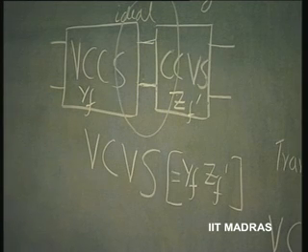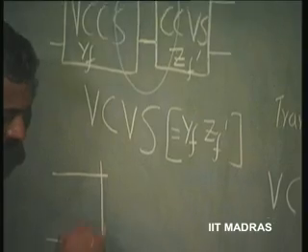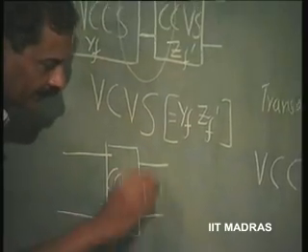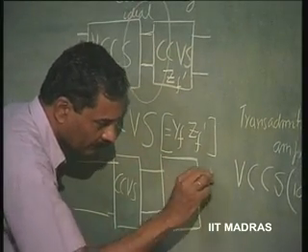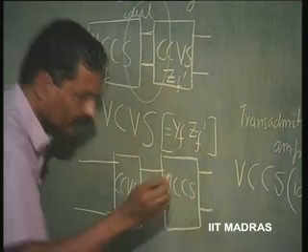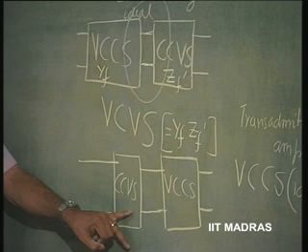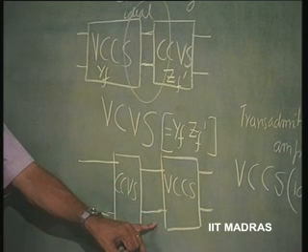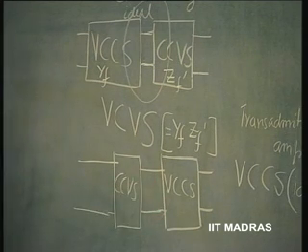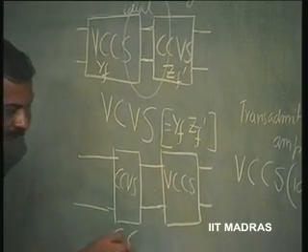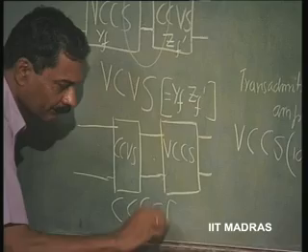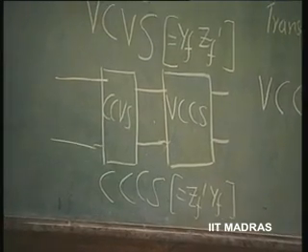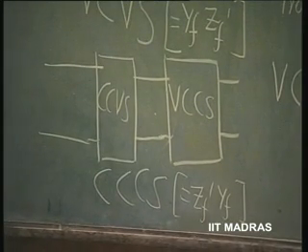Now, this is not all. You can get an ideal current control current source by first putting a current control voltage source, cascade it with a voltage control current source. So, look at it. This is a voltage source, that means source resistance is 0, feeding on to a voltage controlled block which is infinite impedance, right. So, very nicely matched here, and therefore, this is a current control current source with the same ZF prime into YF as the current gain now, instead of the voltage gain.